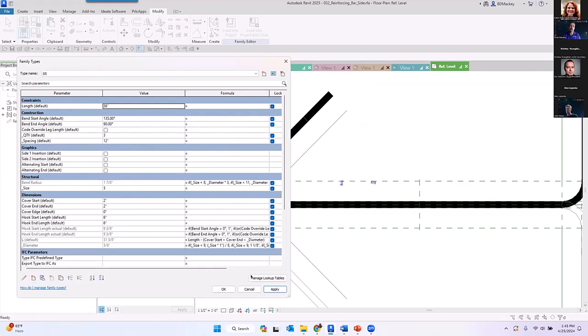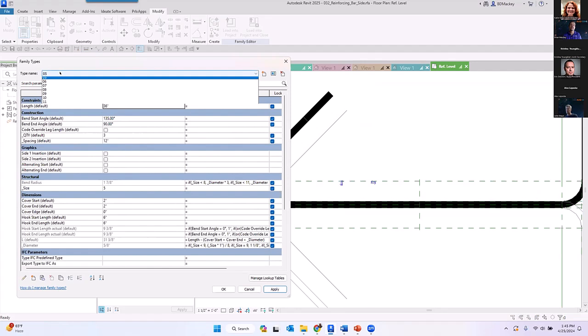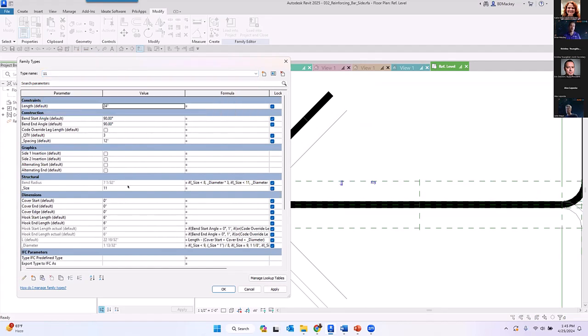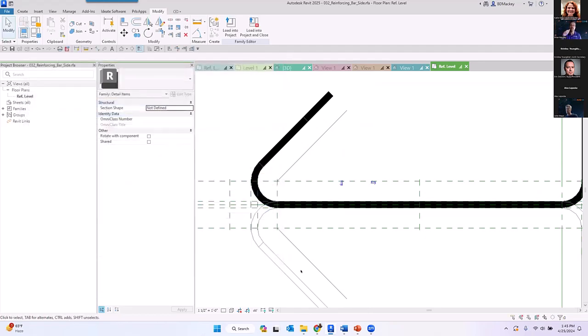Usually when it's broken in the project, it will also be broken within the family editor as well, unless there happens to be several types. And sometimes when you load a family from one project to another project, if you have a type that has a broken value in it, it's not going to display that when you open up the family. It's not going to display it when you hit apply. It's only going to work if you change it to that type. So if I had a family here, I was like, oh, I needed one of these to be a 0 length or something. Revit's going to be like, yeah, I can't create this one instance. So the other solution is open that family, delete all the types, then just try loading it into your project and see if there's something in one of those family types that ended up being broken. So hopefully that answers that question as well.